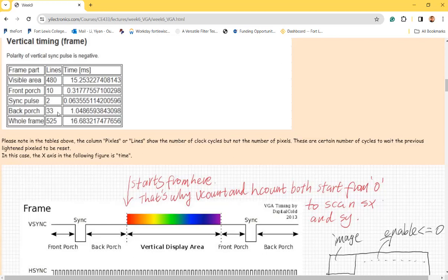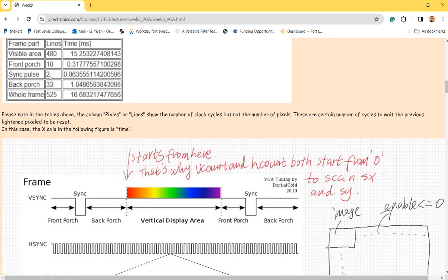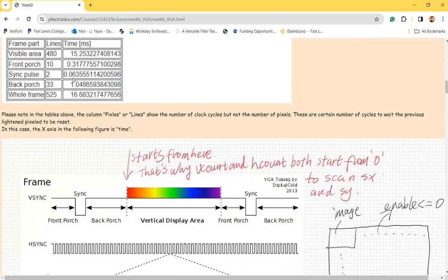When you hear what I'm saying, you can think about how you would code it up in Verilog based on what we have here. It will be a number, right? Whenever the count reaches that number, then we do something. You always have the rising edge of the 25 megahertz clock, which keeps counting as a reference for standard signal. Then you count to these specific numbers to do different tasks.